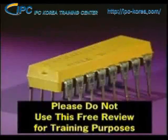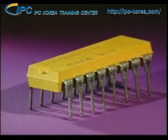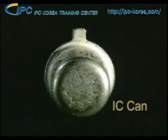The orientation marking for DIPs is either right over pin 1 or on the end where pin 1 is found. As we mentioned earlier, the most common orientation markings are a notch, dimple, wedge, stripe, or number, and the leads are counted counterclockwise from pin 1.